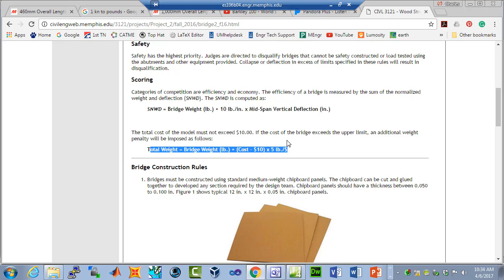Now, how are we going to model this? Well, first of all, we want the displacement at the center, so that's going to be a point that we want to compute. So our SAP2000 model will look something like this. So here's our 22-inch length. I'm going to want a node right in the center, so that's where I can query and get the displacement. I'm going to want one here because that's where I can put my pin support, and also one here. And then I'll need another node at this point. So I'm going to have a very strange looking element. I'm going to have one element that's 1 inch long, and then a 10-inch long element, another 10-inch long element, and then 1 inch.